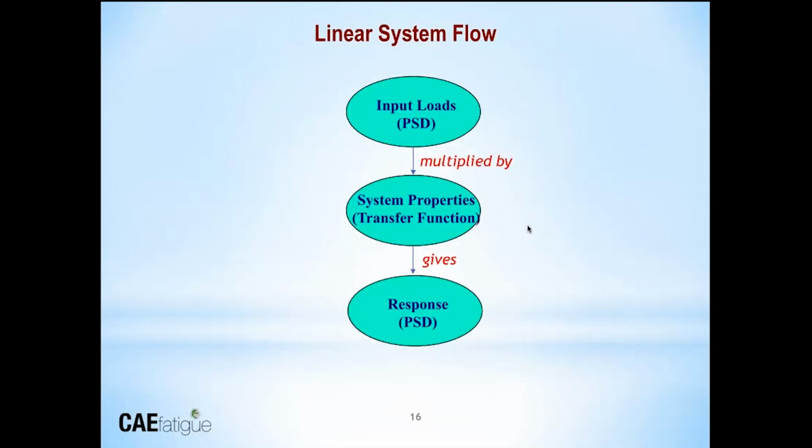Now that all fits into the analysis flow where we have input loads, these PSDs we've been talking about that were originally perhaps time histories, but some people start directly with PSDs. Then we need something about the structural system in the form of transfer functions. But that's where our solvers come in. We're talking about Nastran today. That's where Nastran comes in. It gives us those system properties. And then we combine these two in a simple multiplication to get the response PSD, or response PSDs, because there'll be more than one output point. And those response PSDs are then reduced down into the moments. So you see that analysis process and the moment calculation now become very simple computational tasks.